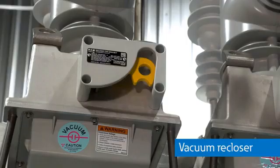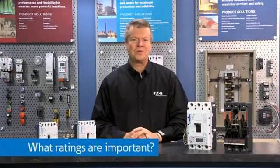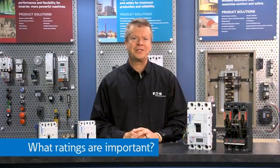In addition, they use circuit breakers with a different form factor on their distribution circuits. They use vacuum reclosers, which are just vacuum breakers in substations or on a pole, and vacuum fault interrupters, or VFIs, inside substation and distribution transformers. Essentially, the VFI is a vacuum breaker that uses an external relay for protection, but is installed inside the transformer tank. What ratings are important when deciding what circuit breaker to apply to your system?